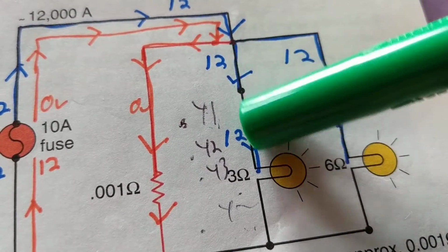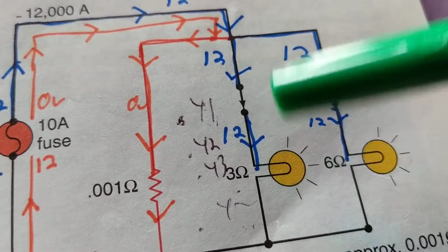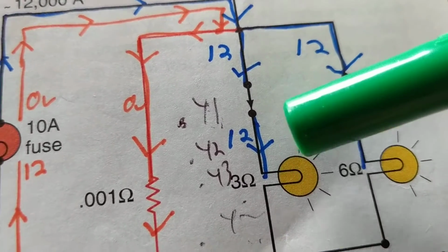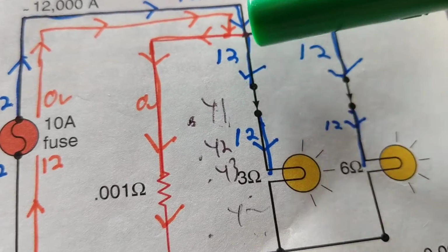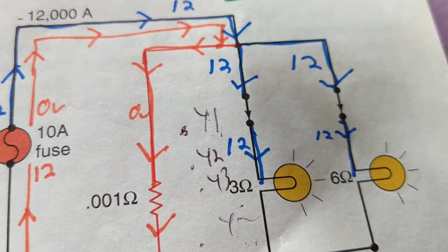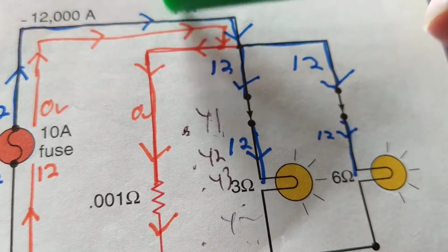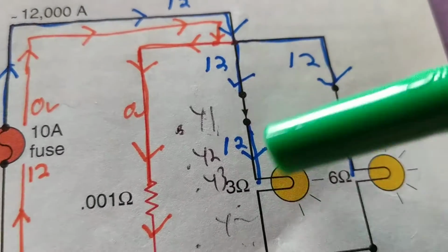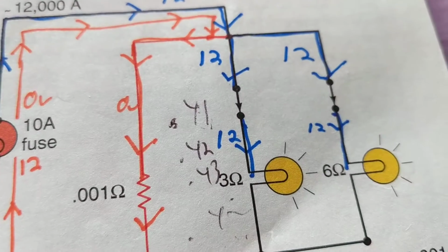If I see the left brake lamp out, the first thing that comes to my mind, obviously, is the bulb, right? Let's say I change the bulb. Then I have to look for an open. Where? Here? Nope. You're not going to find an open over there. Why? Because if there's an open over here, it'll knock out both lights. You only have the problem with this light out. What will cause that? This wire over here.